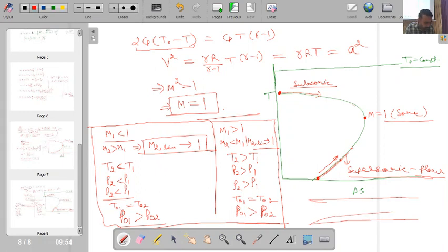So this boundary layer along the length of the pipe will keep on growing, and we will see within the boundary layer our velocities are very small, and in between this our velocity is high velocity. Okay, so not free stream, because for continuity equation to balance, our area is decreasing, that velocity has to increase. So here we will be having higher velocity.